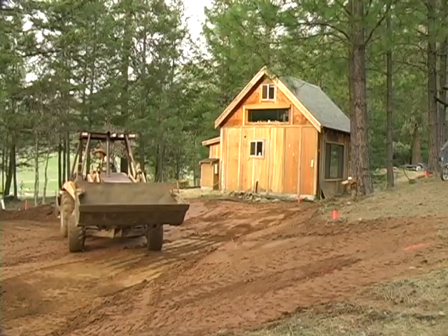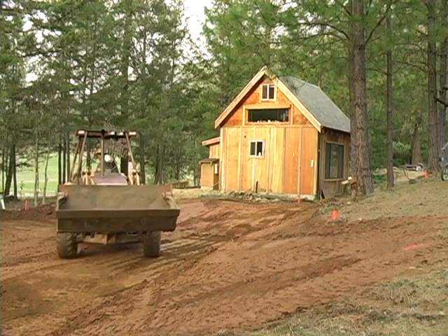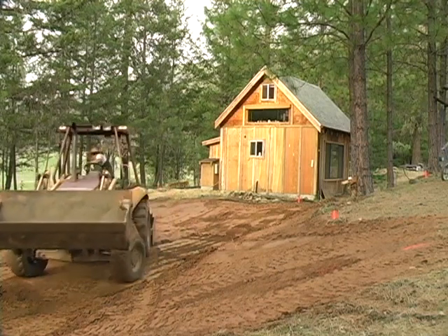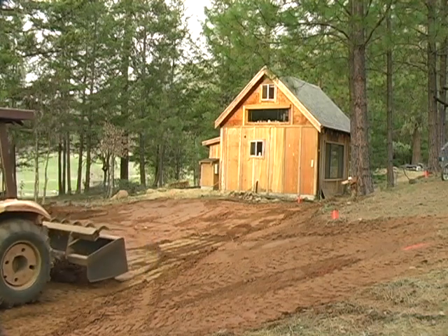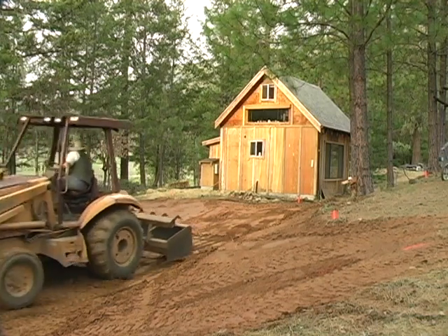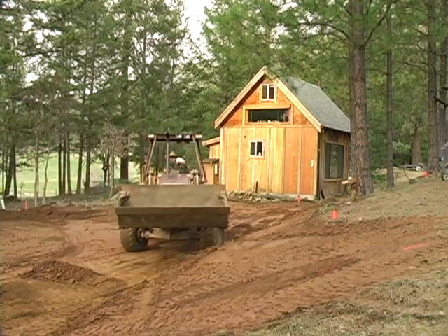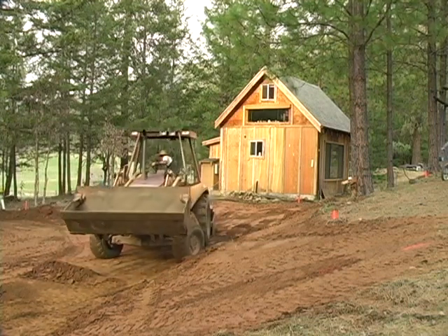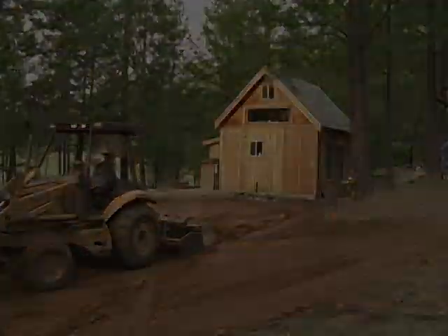Our rough grade is still a bit high, so we're going to continue working it with the skip loader until we get closer to our target. And we'll want to continue to check points in the field as we do this so we don't overcut and end up too deep on our finished grade. It's pretty much impossible to get a perfect level grade here, so we'll get as close as we can, and then we'll come in with some compacted gravel to clean up any irregularities in the grade itself.